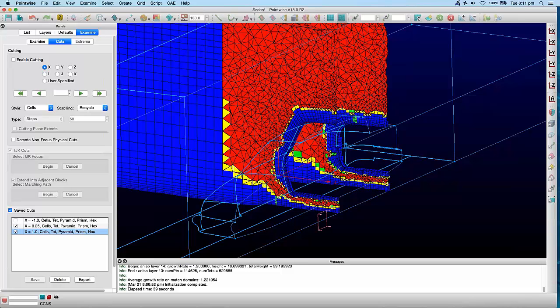I've got a question here, but I've just got to expand it so I can read it. Can you find the drag coefficient directly without doing CFD? You could probably do that by working out a frontal area for the car and then from the actual coast down. Yeah, the coast down test. It's actually surprisingly good.